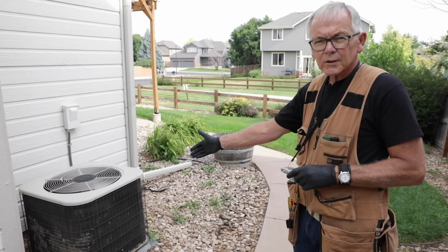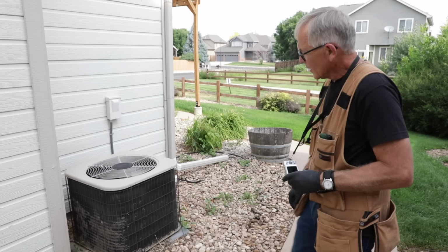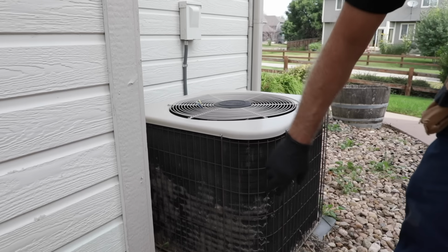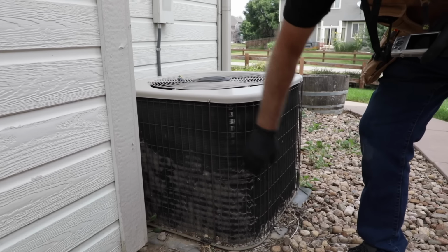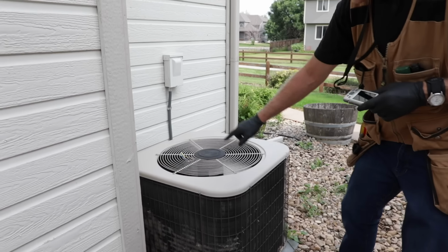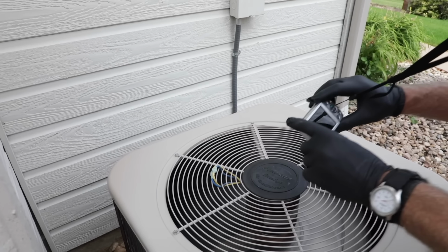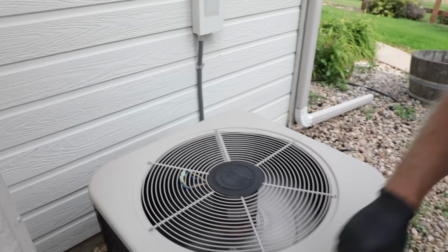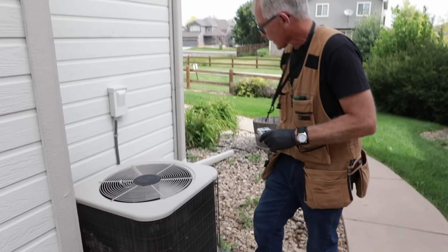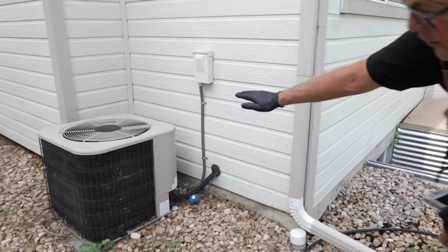We're outside here at our condenser. I'm going to take a reference photo. One of the things I can see is we have some buildup here on the coils. So I'm going to recommend a cleaning of the coils. This will really affect the efficiency of the unit. The other thing I can see up here at the top is some wires sticking above. I'm going to go ahead and document that. And I'm also going to take a photo of this debris for our report. I'm going to come around here. The unit seems to be pretty level.